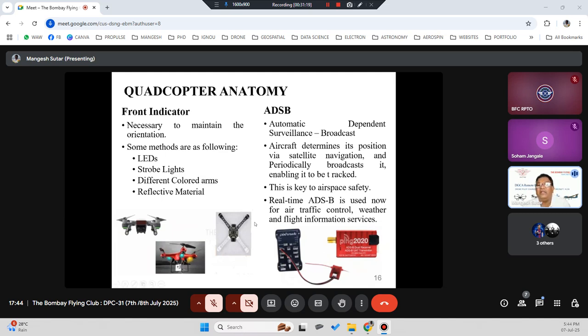This module might cost like 20,000 or 40,000 rupees, even 80,000. This will unnecessarily overload the cost when you are not going to use this functionality itself. That's why, as of now, none of the type certified drones has this module. That's why the DGCA is also not making it mandatory, because that ecosystem is not there. Once you have the ecosystem, and the procedure to operate and use it, only then is it viable to have this kind of component on your drones.